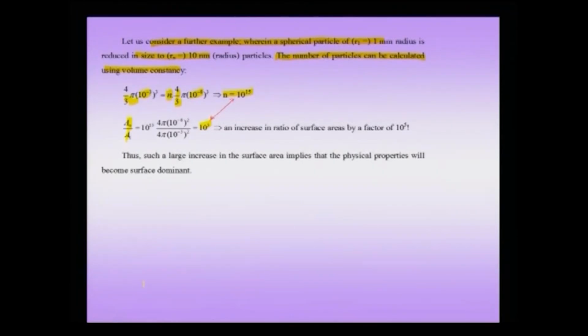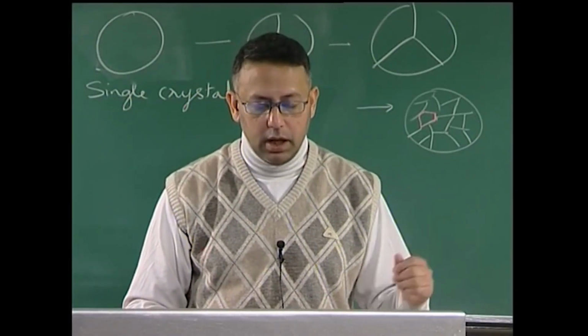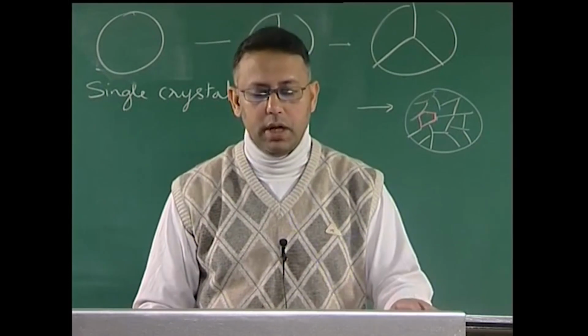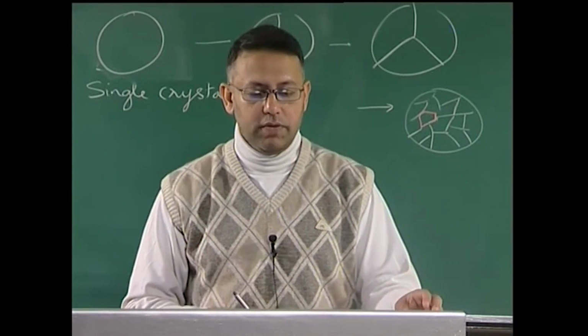And this is directly leading to what we have been reiterating many times, that such a large increase in surface area implies physical properties will become surface dominant. So, there will definitely be a contribution from the surface in any one of the physical properties you are talking about, let it be plasmon resonance, let it be adsorption of gases, let it be creep in the case of a polycrystalline material. All this will be dominated by surface or interface effects.